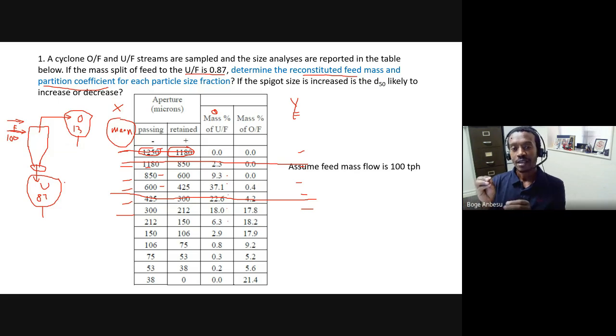But regardless, here we don't have any material transported from one place to another. The overflow is captured in a pipe, the underflow is captured in a pipe. As long as you sample that properly, there shouldn't be any loss, essentially. So that's why we don't assume any potential losses in underflow or overflow. Whatever you add up between the overflow and underflow should give you the feed.